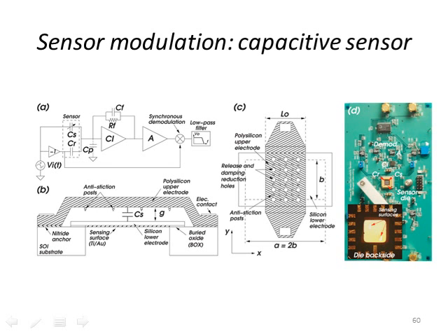The sensor that changes is CS, and then there is a reference temperature capacitor that does not change. We multiply one of the capacitor signals by -1, and then we send this into a charge integrating amplifier. You see CR, and then it has a feedback loop, which is CF-RF.